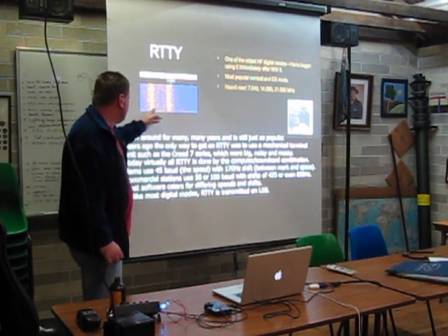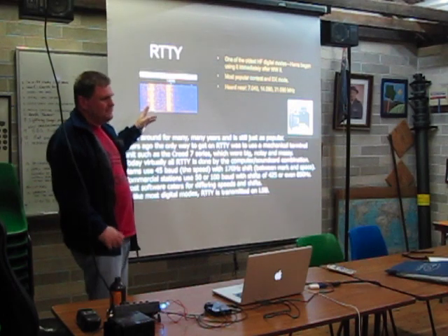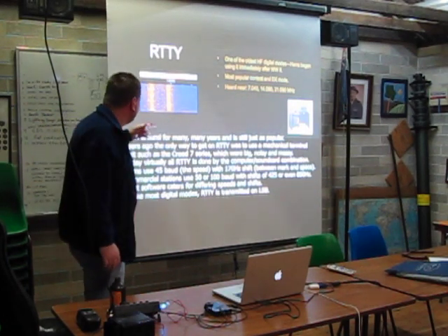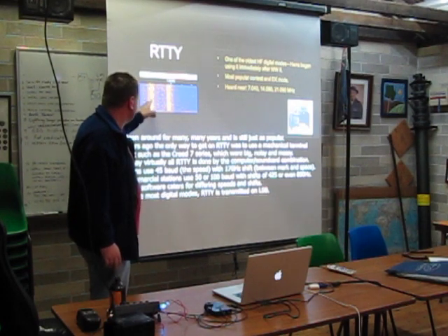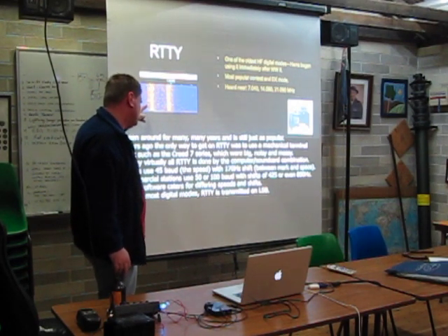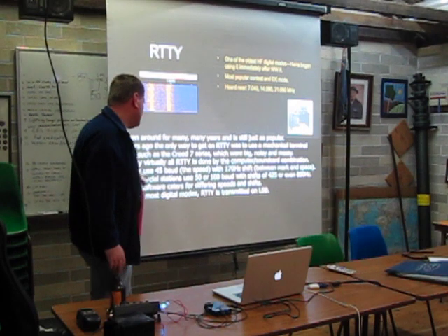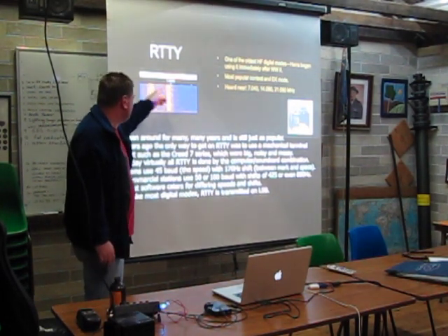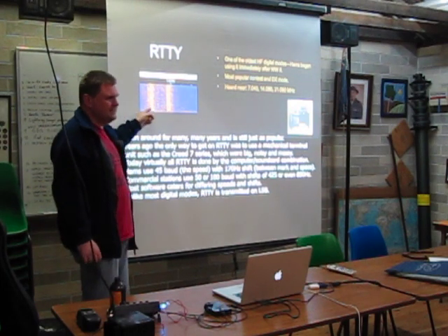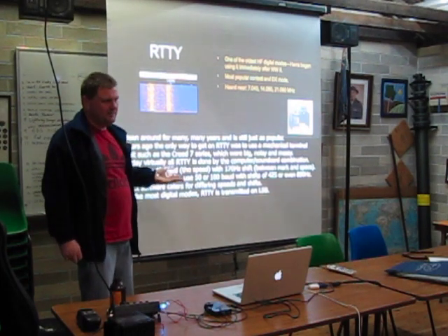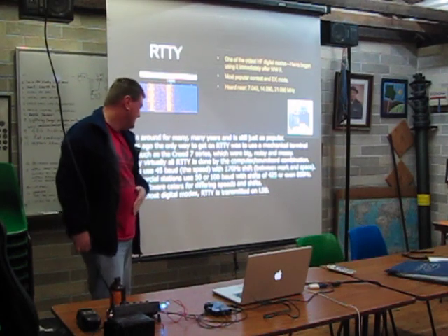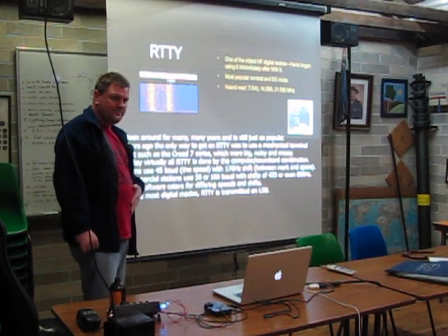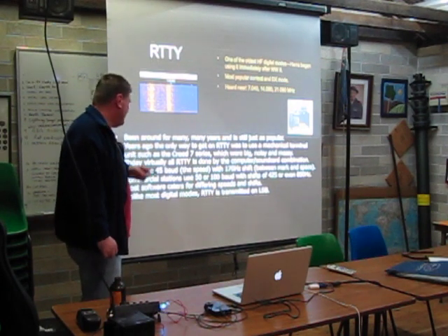and so it works by using frequency shift keying. The previous one we talked about swapping the phase of the signal. Here we have two tones, so I forget what the exact tones are, but they're spaced by about 170 hertz. So by switching back and forth between a high tone and a low tone, you can generate binary ones and zeros and represent your different characters. Are the characters all the same width? Yes. RTTY? In this mode they are. Okay.